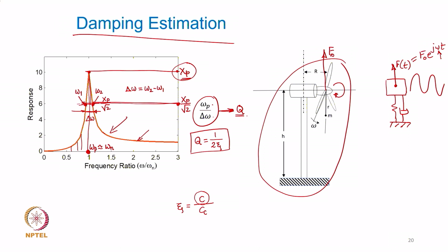What is the alternate method, other than what we are discussing here, of finding out the damping in the system? You remember? Suppose there is a beam here made of steel, and I want to know the damping factor of this steel beam as a vibratory system. Maybe the beam has a mass sitting at the tip. What I typically do, you remember the logarithmic decrement that we discussed. So, I perturb this beam. I basically give a gentle small tap, or displace it and then release it.